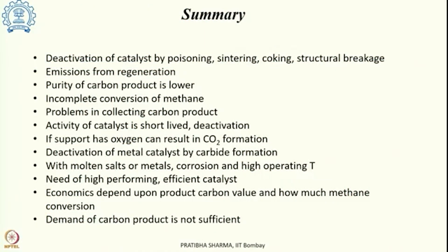In case of molten salts or metals, corrosion as well as high operating temperature is the challenge, and new catalysts which are highly efficient, with reduced sintering and deactivation, are required. When it comes to the economics of the process, that depends upon the conversion of methane, and at the same time the value of the carbon product which is obtained in the process. Currently the demand for the product is not very high, but it is expected that demand may grow, and with a better catalyst this method could be commercialized. So, that is about the decomposition of methane process. Thank you.